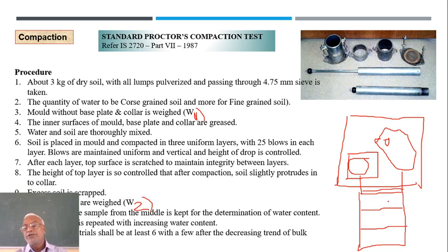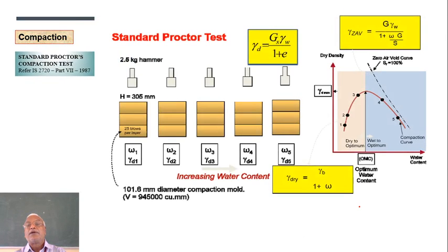Now next what you do is you remove all this soil back. Now anyway you have added some water content, you add a little more water, mix it thoroughly, repeat the procedure. You have added the water, right? Because of that, it may so happen that the density would increase. Obviously it increases. Okay, again some sample is kept for water content, and then the density is noted down. Now how the noting is done, that is explained in this. Here there is an explanation in pictorial manner.